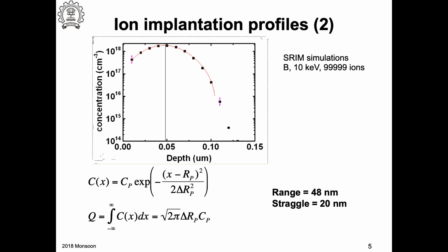So now lateral straggle is important for scaling of the MOSFET. What is my gate length? Is this the gate length? This is the gate length, right? But what is important for scaling is the channel length. And this is my metallurgical channel length. That's small, and this decides the short channel effects. My gate length is defined by lithography and etch processes, but if I have a lot of straggle, then I have a problem, because I will not be able to make a very short device.